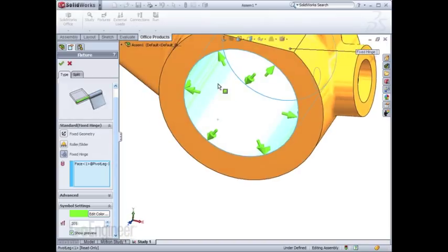You can see that we have a directional restraint all along the cylindrical face in the radial direction of the cylinder. So the cylinder won't be able to expand outward or contract inward. Don't forget that the arrows represent a restraint in the positive direction of the arrow as well as the negative direction of the arrow.